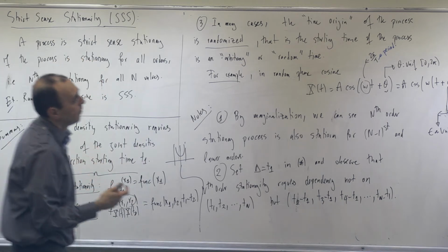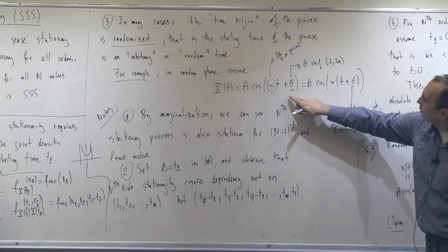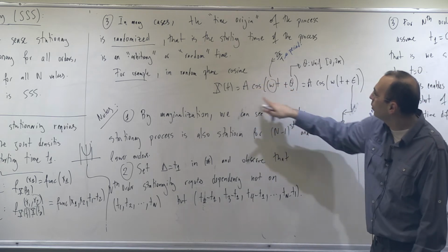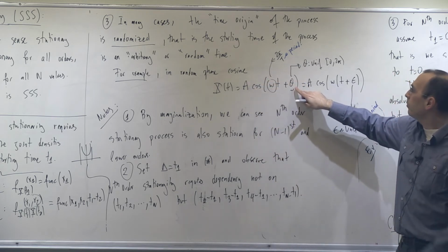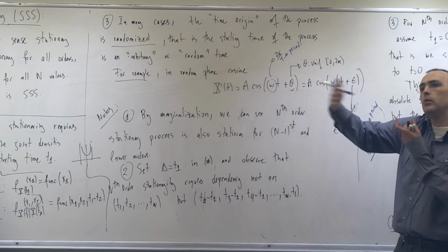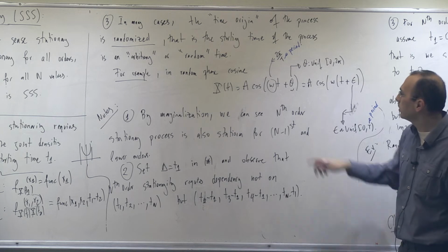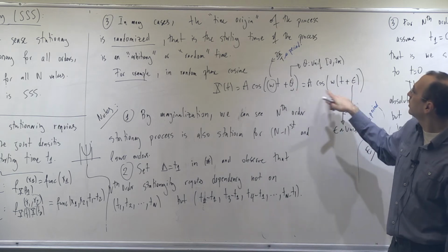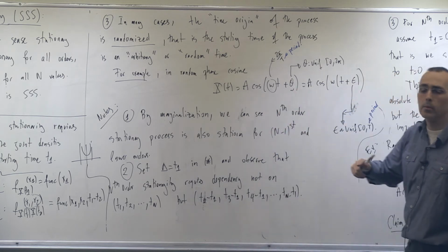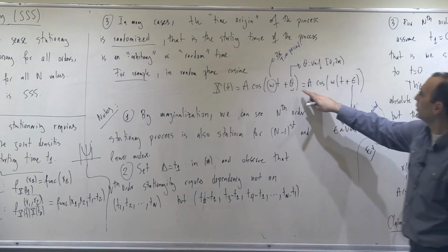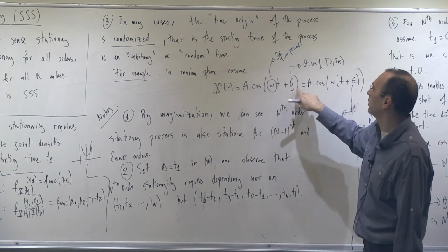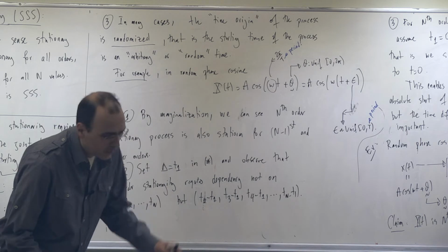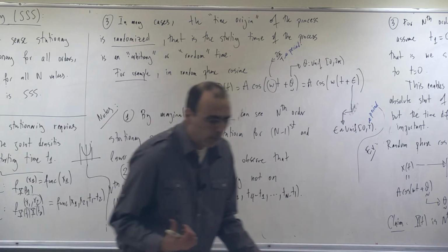Now you have a signal which you may model with a random phase. The incoming signal is this, maybe this is a radar system. I have transmitted this kind of waveform, but the received waveform has a random phase because this is related to the propagation delay. Or a simpler example: you turn on your oscilloscope, and suddenly at some time it starts showing a cosine waveform. But the issue is that the time origin, the initial phase, in this case for the cosine, becomes randomized. In some examples this will be very explicit. In others this will be our assumption.